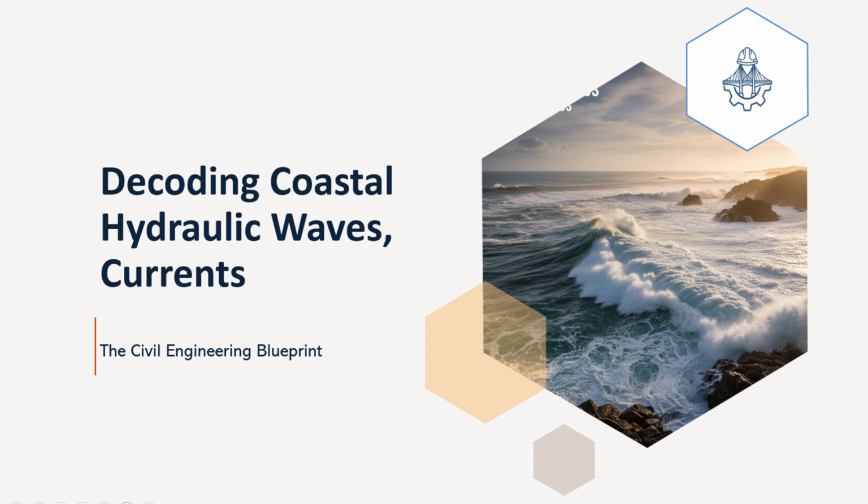Indeed. Now, to truly understand how these parameters fit together mathematically, we turn to the governing equations and boundary conditions. These are the fundamental physical rules that define the behavior of these idealized waves. We start by assuming irrotational motion of an incompressible fluid. So incompressible fluid means the water density remains constant, which is a pretty good assumption for ocean water in most cases. And irrotational motion means no swirling fluid particles, no significant turbulence or vortices within the flow itself. That simplifies things quite a bit, right?